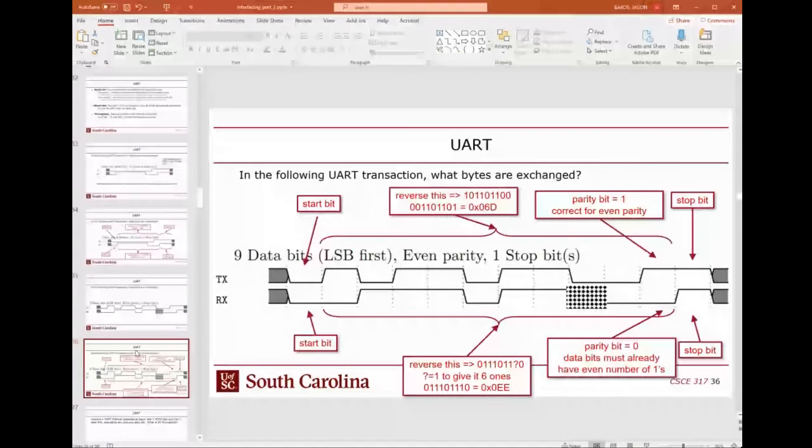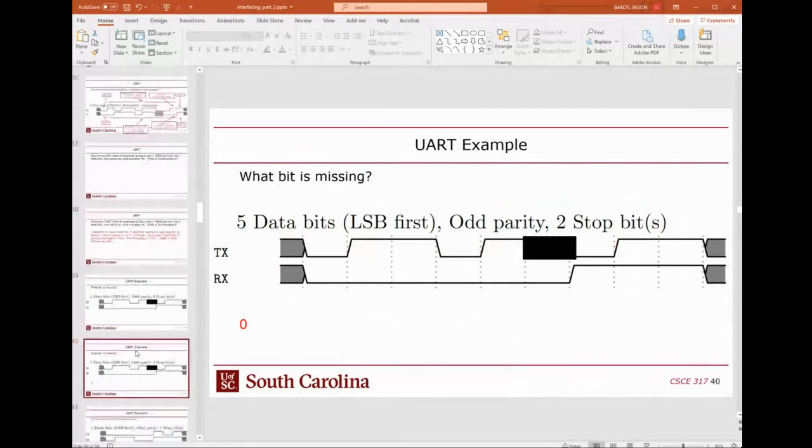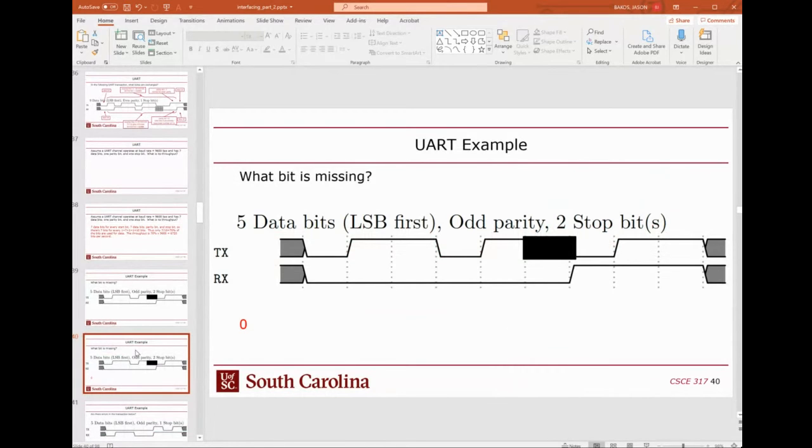Okay, so that kind of maps that out. There's an example. In this case, we had a missing bit. Normally, in practice, you probably wouldn't know if there's a bit missing. Typically in reality, the bit would be corrupted, right? You'd have a bit that would be received differently than it was sent for some reason. And so generally speaking, you use the parity to detect this. The problem, of course, with parity is that you could have 2 incorrectly received bits, and then the parity wouldn't